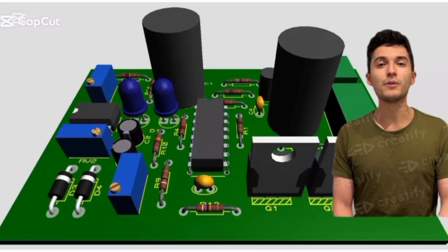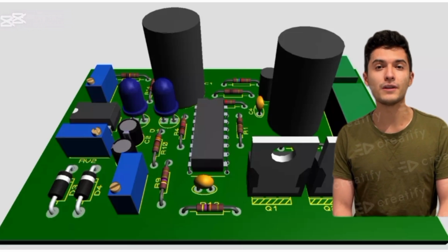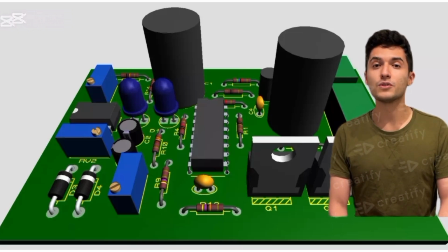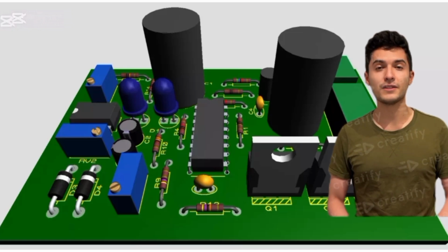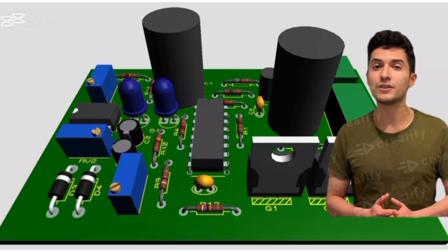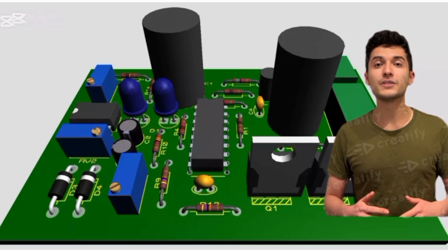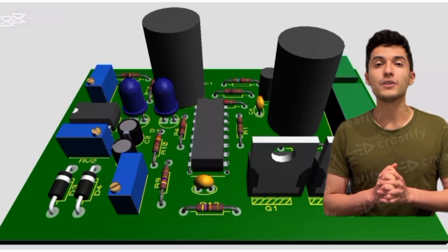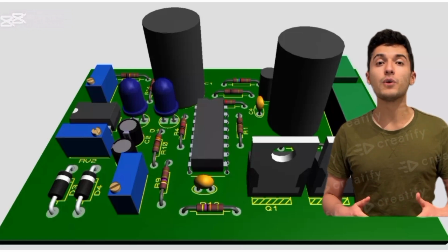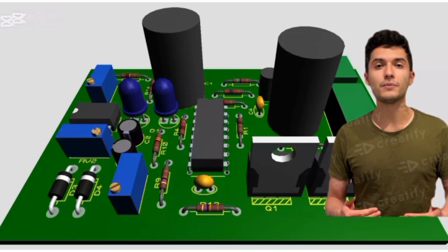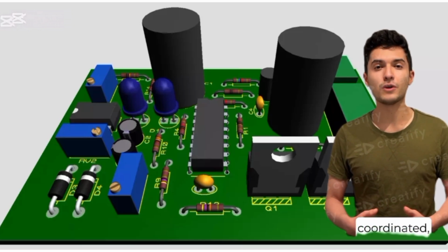Now let's pause for a moment and look deeper. The oscillator might seem like a tiny section of the inverter circuit, but it's actually the timing brain behind everything. It controls how fast the switching devices turn on and off, setting the rhythm that defines the entire operation. When the oscillator runs steady and accurate, the inverter delivers a smooth, clean AC output. But if the frequency drifts or becomes unstable, the output turns rough and noisy, affecting both performance and efficiency. So, in simple terms, the oscillator doesn't just start the process, it keeps the inverter alive, coordinated, and consistent.